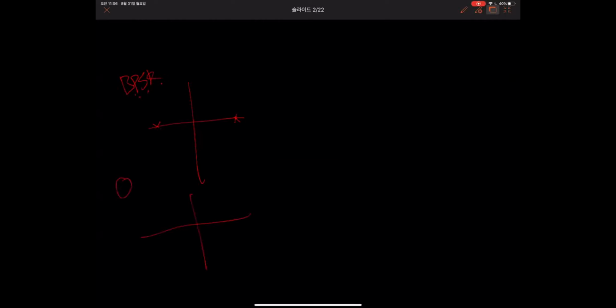What if I'm using QPSK, quadrature phase shift keying? Meaning I can send this and this information: 0 0, 0 1, 1 1, and 1 0. If I'm sending this information, my receiver may receive this, and I can translate it as 0 0.